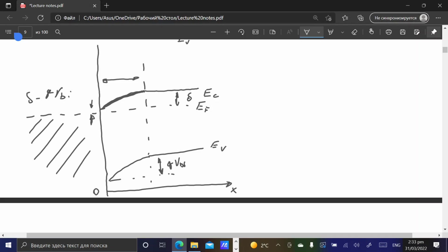So it's kind of not a big difference, just manipulating the work functions of different metals with the same semiconductor, but you see how fundamentally different a result we get at the output. That makes a huge difference depending on what you want to achieve by introducing this metal-semiconductor interface into your device.